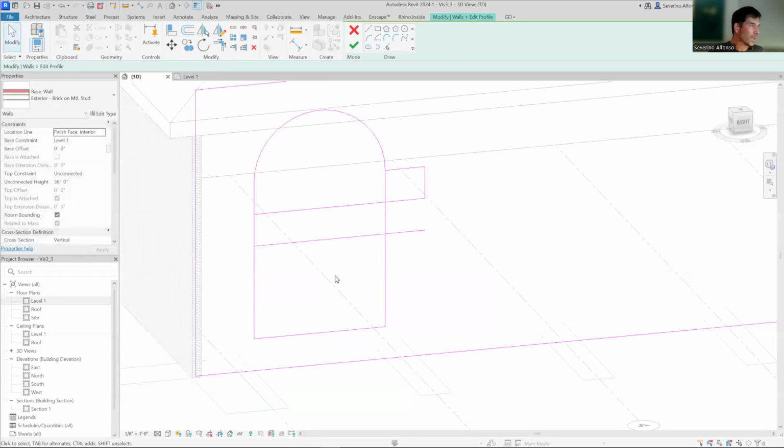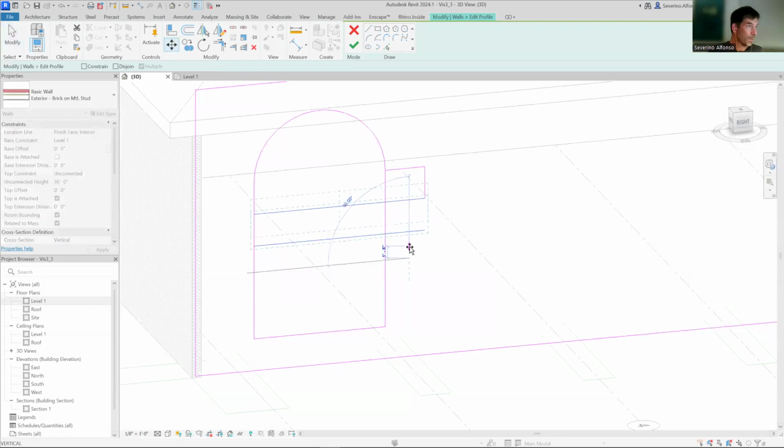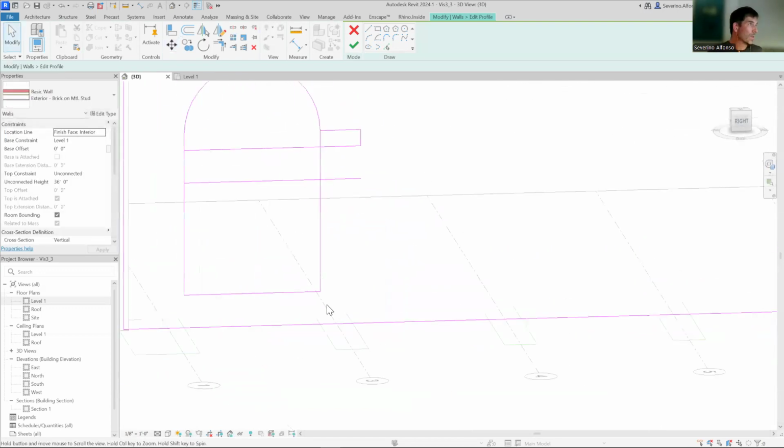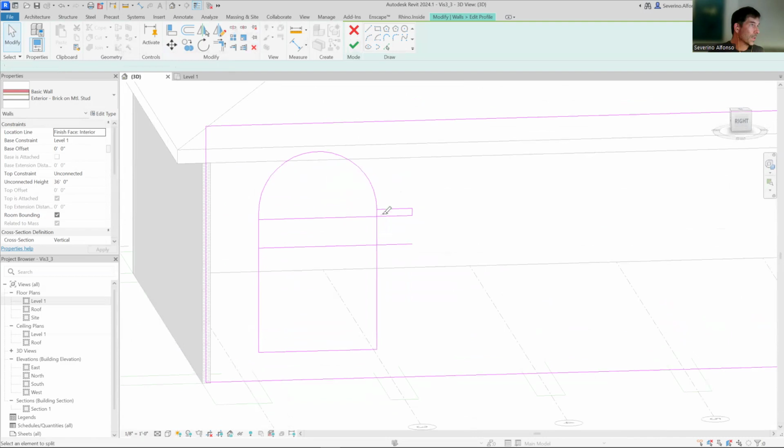Yeah, you see, it doesn't really feel that proportion. So once I select those two and move them up at least 2 feet and see how that looks. I think it's better, maybe even moving it another foot up. And I think that's about right. So I'm going to split, SL, here and here, and TR for the trimming option.